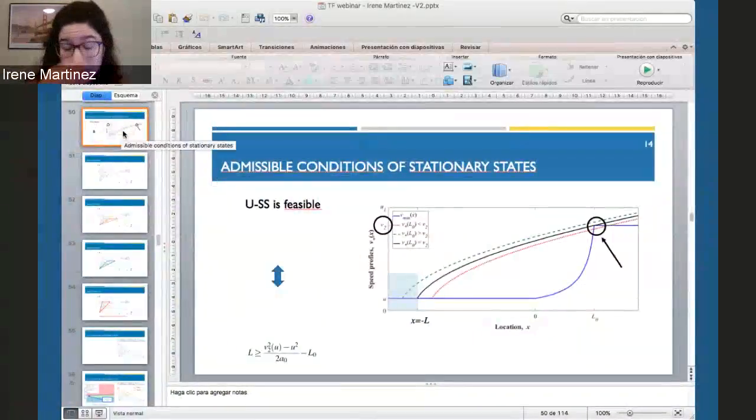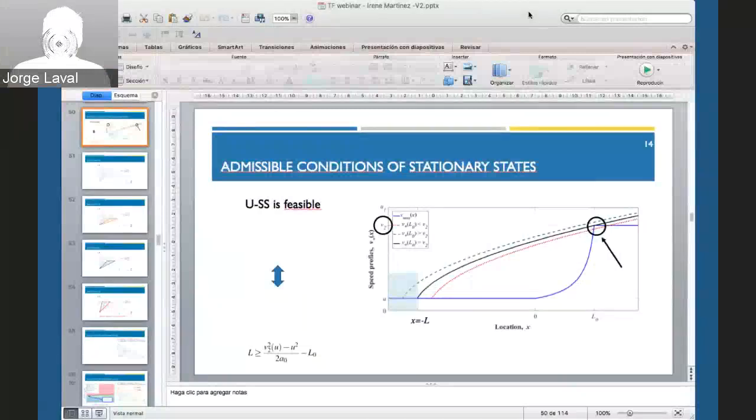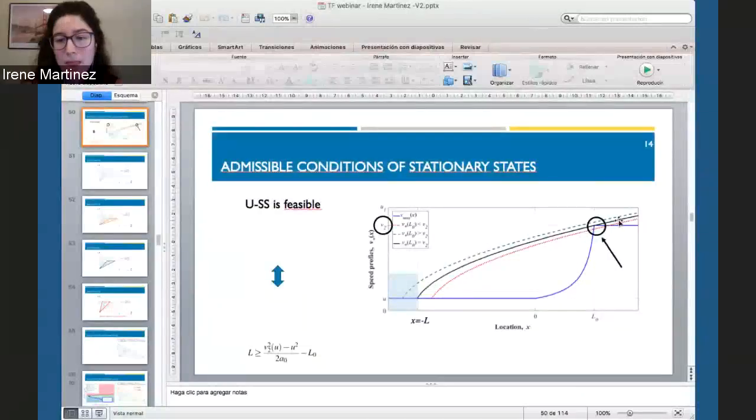So here we see the minimum speed. I'm showing the slide, right? Yeah. I'm showing the minimum speed in blue, and because this function is concave and it's constant outside of the bottleneck, when we have any given bounded acceleration model, the idea is that we want the vehicles to accelerate freely without slowing down, so that the density, in a sense, is low enough for them to travel at the maximum acceleration until they reach the free flow speed. So this is the bounded acceleration state with the different colors.